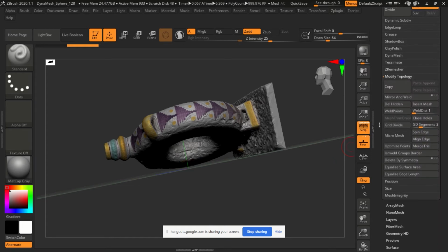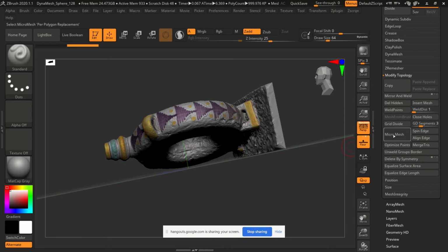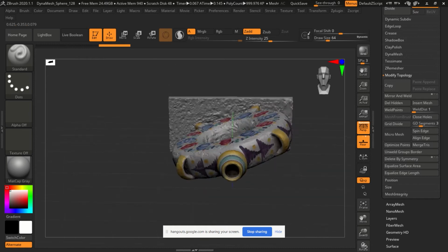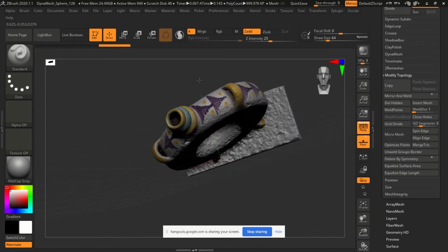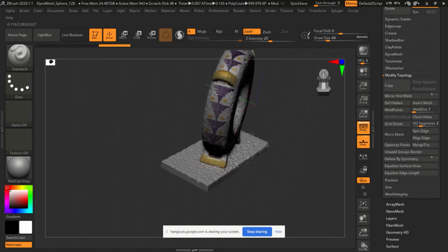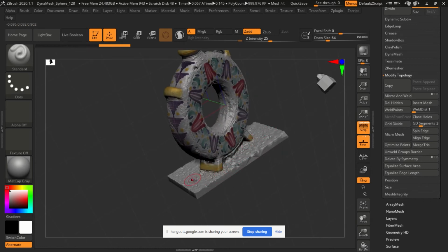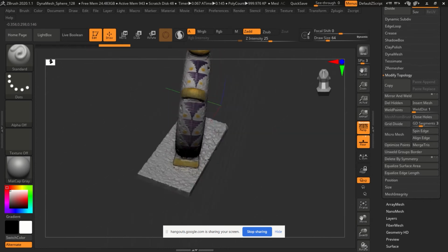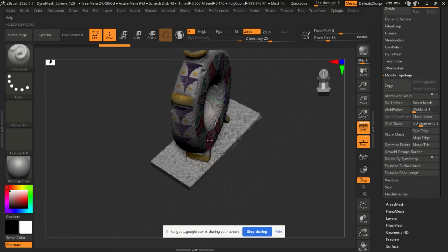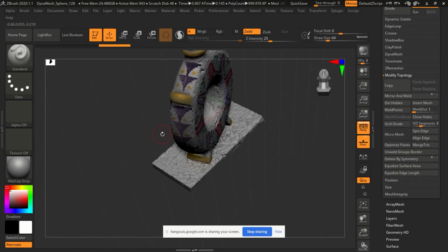Okay, let's open up this menu. Here, I'm going to hit weld points. This will weld any points that are on top of each other. As well as here, I can do some cropping. So if I want to crop this bottom platform that the Flask is sitting on, I can do it in two different ways. So I can either use my selection tools. This is what I showed in the last workshop.